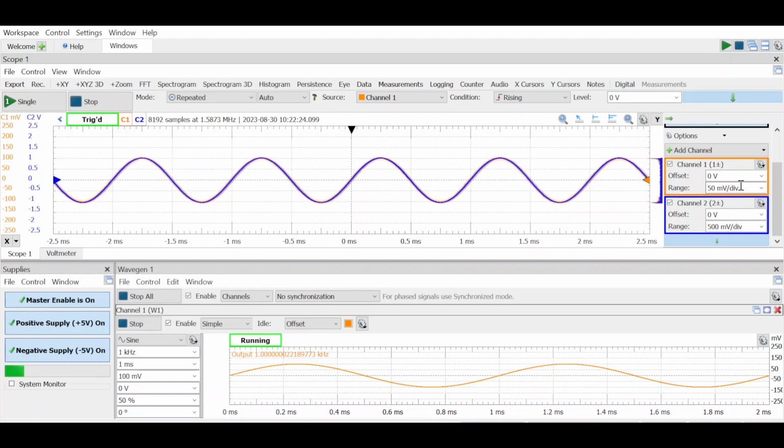when the oscilloscope is set for 50 millivolts per division. Now the output appears to be almost identical to the input, and the output is set to 50 millivolts per division, which implies that we have a gain very close to 10. Consequently, we can assume that our non-inverting op-amp is not loading down the signal generator. Let's go ahead and switch to the inverting amp and see what that looks like.